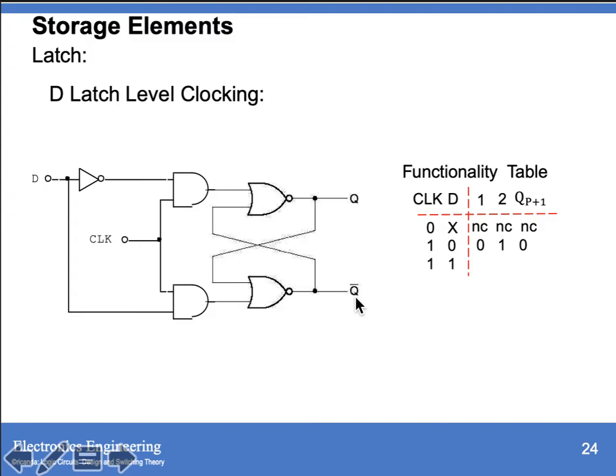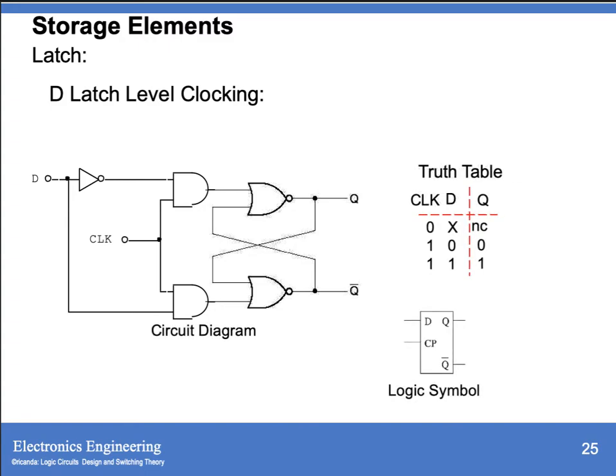And if we have 1, if this is 1, so this is 0. So we have an output here equal to 1, making your NOR gate 2 equal to 0. 0 NOR with 0, then your NOR gate 1 equals 1. So this is your truth table. If your clock is 0, that is no change. If your clock is 1, then your Q will follow what is in your D. So that is D, to eliminate the race condition of your RS.